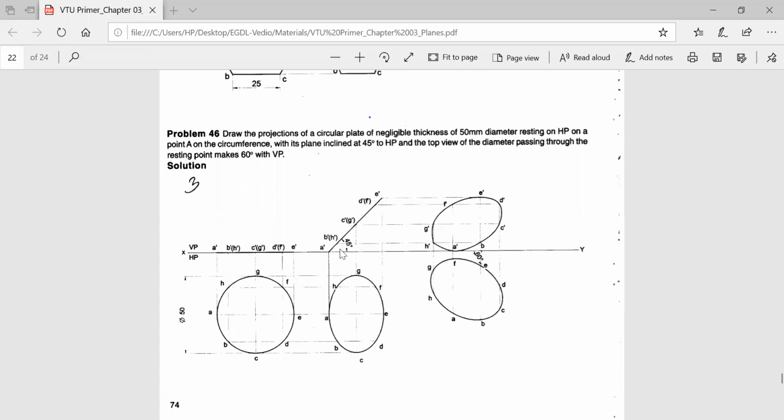So you leave some space, fix a point as usual. From this point you take 45 degrees using the protractor. After you draw the line, you measure this distance, how much it is. From A dash to E dash, measure the distance using a compass. Don't go with the scale. Keep one end of the compass over here and cut an arc. So after you cut an arc, name it. So this is A dash and E dash.